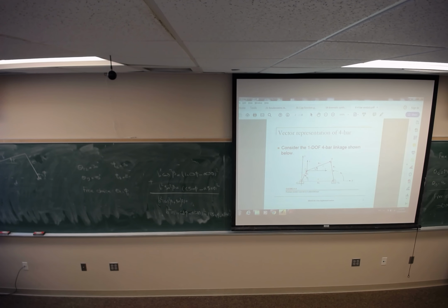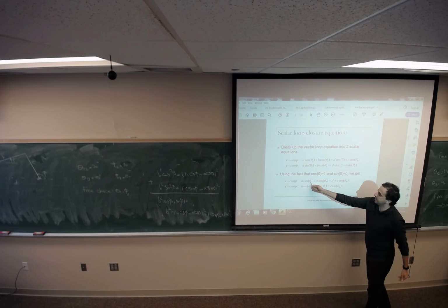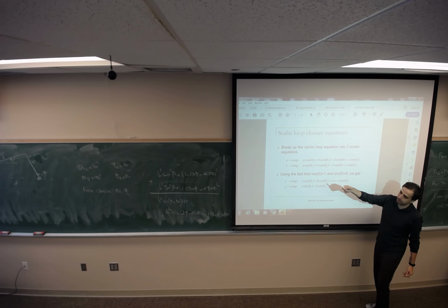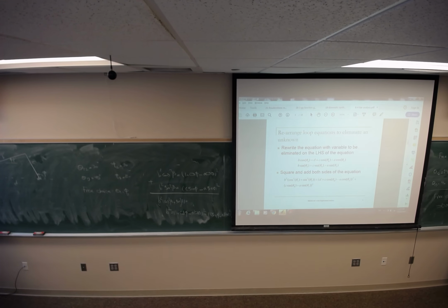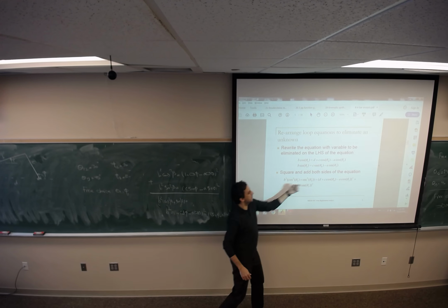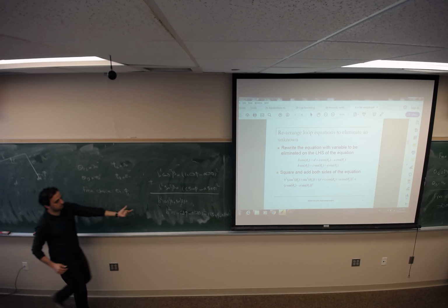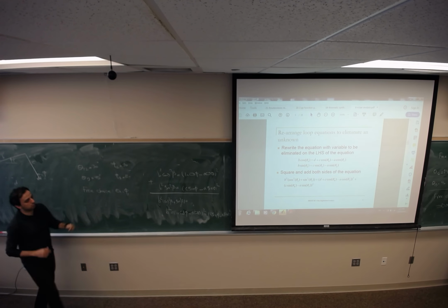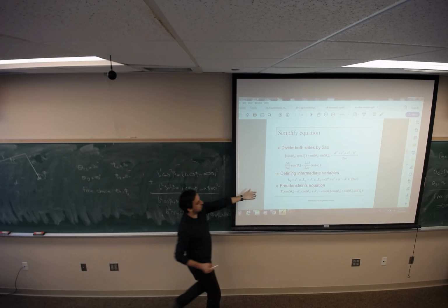So this is what we did in the 4-bar mechanism. The same thing. Theta 2 is our theta, theta 3 is the beta, and theta 4 is phi. So what we did, the same thing: A squared times this equals the right hand side. On the next slide, I'm going to show you how we simplify this. Since I don't want to rewrite them again, I'm just going to the final equation, which was the Freudenstein equation.